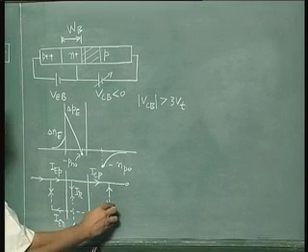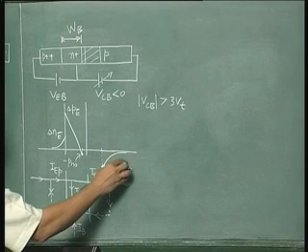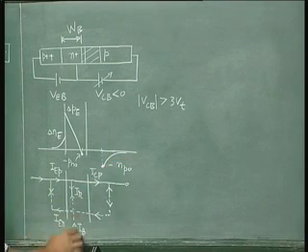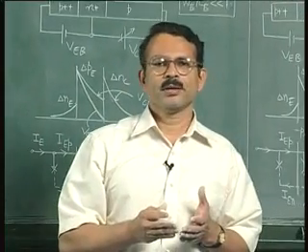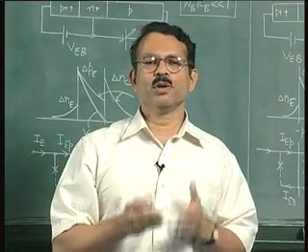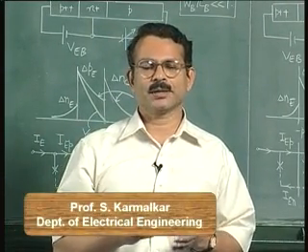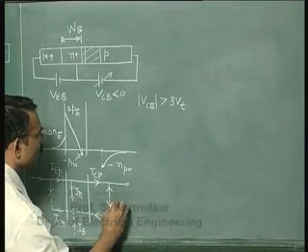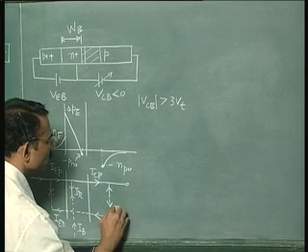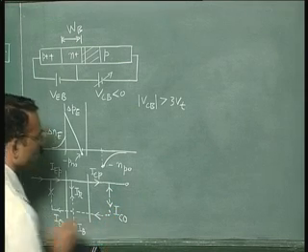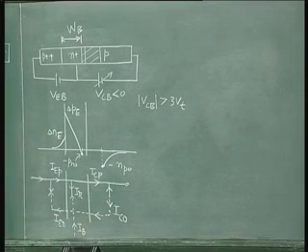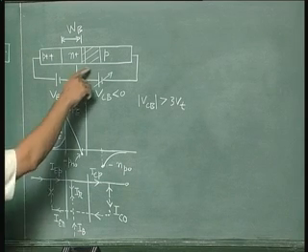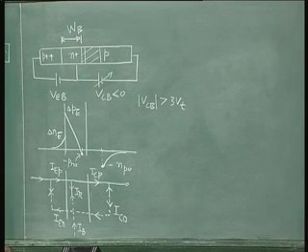but this current will be small because it is only dependent on the minority carrier concentration, and it saturates. You know that the reverse current across a diode saturates, okay, if you neglect the generation within the depletion layer of that junction. So this is the so called ICN. Now we will show this by the symbol ICO, which is commonly used symbol for the reverse current across the collector base junction of the bipolar transistor.